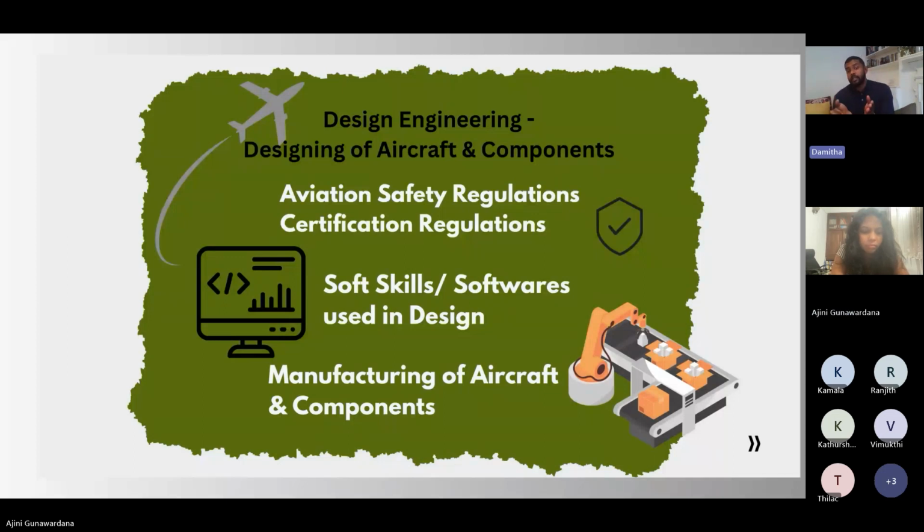So there are certain thicknesses that can't be bent at 90 degrees, so you can't achieve that radius. You need to be mindful about these things when you create a design, whether it could be manufactured, and when you do the manufacturing, does it require very special machines to achieve that requirement? So you always need to find a balance between innovative, creative designing and the achievability